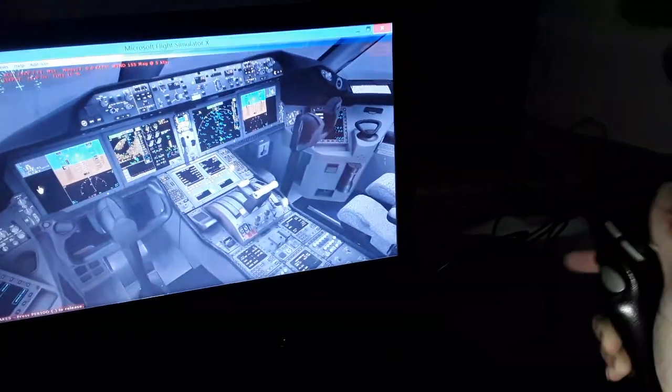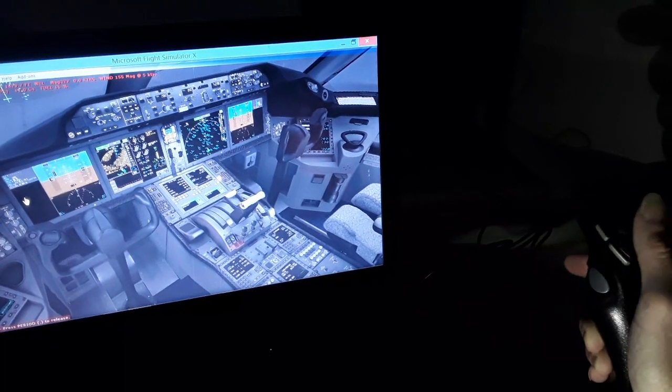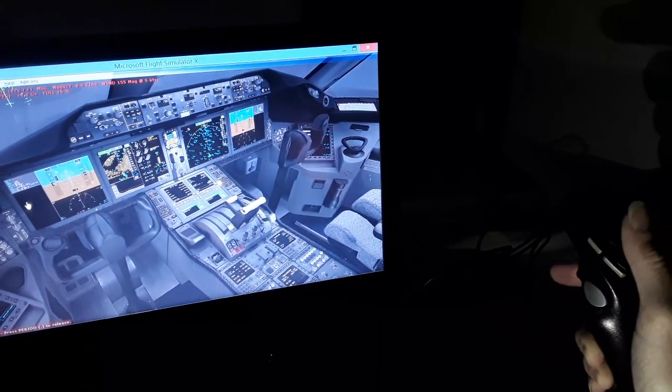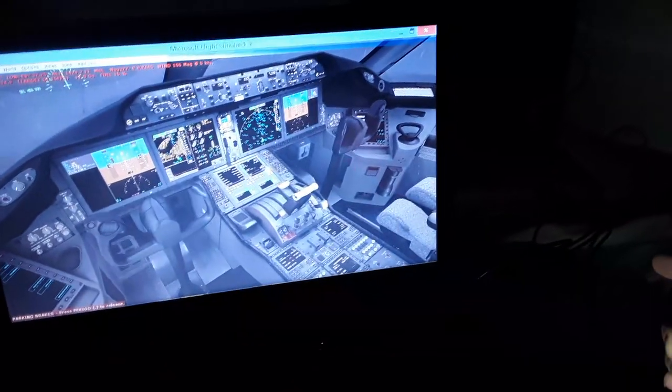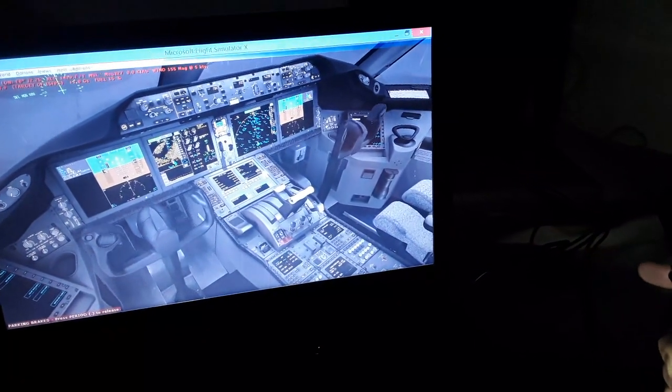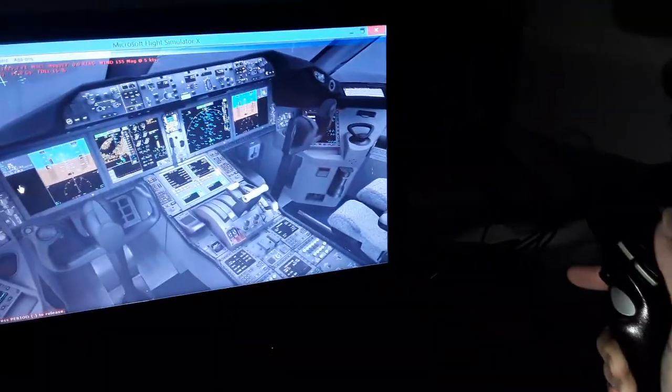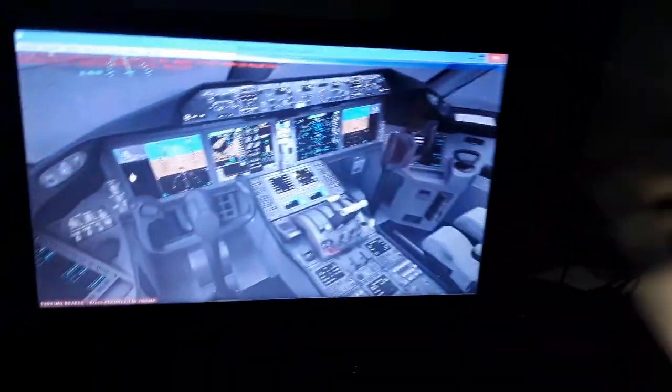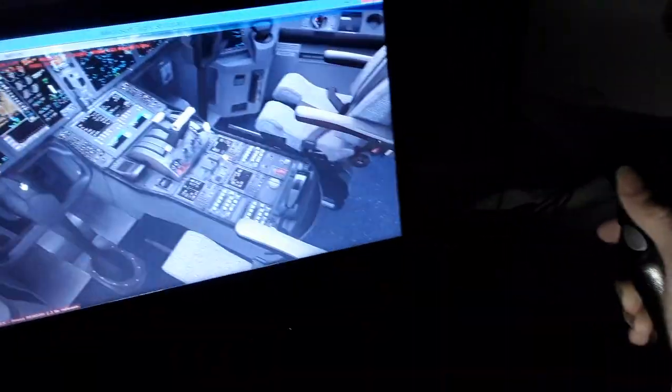Then the rudder is aerodynamically effective above 45 knots, while the nose wheel deflection decreases all the way to 0 at 70-80 knots. After that you have only the rudder, aerodynamically effective for flying, for takeoff or for landing, instead of the nose wheel. So this is all you need to know. You also have the toe brakes, which you press on the top surface of the rudder pedal. So this is all the flight controls.